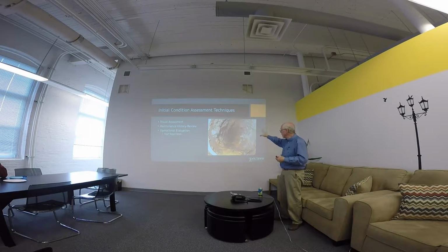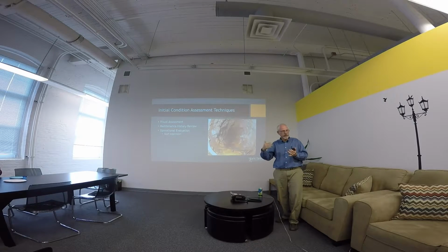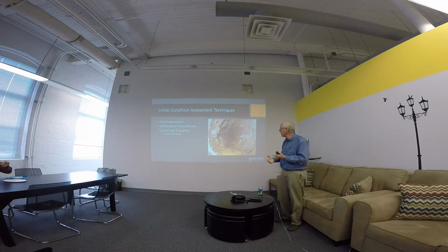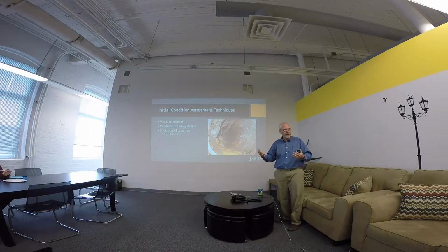One condition can be your level of service, what are you providing? Color is measurable, so if you have color in your water at a certain level, it's not acceptable. So that's a condition: is the asset providing that service? You could have color, you could have iron, staining of your sinks, toilets, and everything else. So it's not providing the level of service.